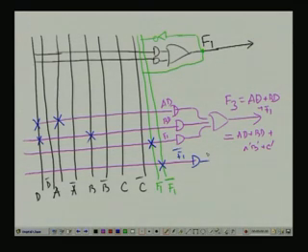So, here we have seen one advantage, one special type of PAL structure, where the output of the fixed OR plane is again fed to the input of the programmable AND plane, and in that way it extends or increases the programmability as well as the design variety of the PLDs.